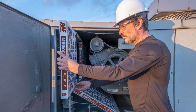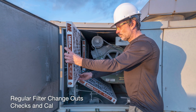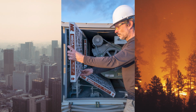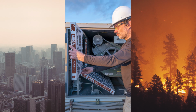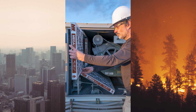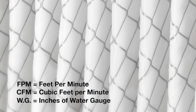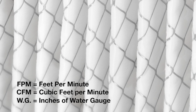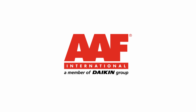It's very important to ensure that a regular changeout schedule is adhered to, along with regular checks and calibration of the Magnehelic gauges. Unusually high pressures can occur if there have been high particle counts in the air recently due to events such as wildfires, local construction, or seasonal variations. FPM, CFM, and WG are terms you should know when ensuring that you maximize protection while still keeping your energy costs low. In other videos, we'll review more about pressure drop and how it's affected by the design of the filter.